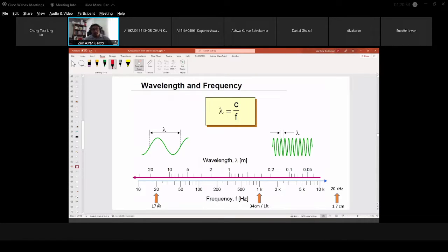Okay, basically almost 4 meters of foam length is needed to absorb the sound properly at this frequency. So that's the reason why most of the time when we use porous material, we are absorbing sound mostly in the high frequency range and not in the low frequency range. For the low frequency range, we need a different strategy. Absorption might not be the right strategy.